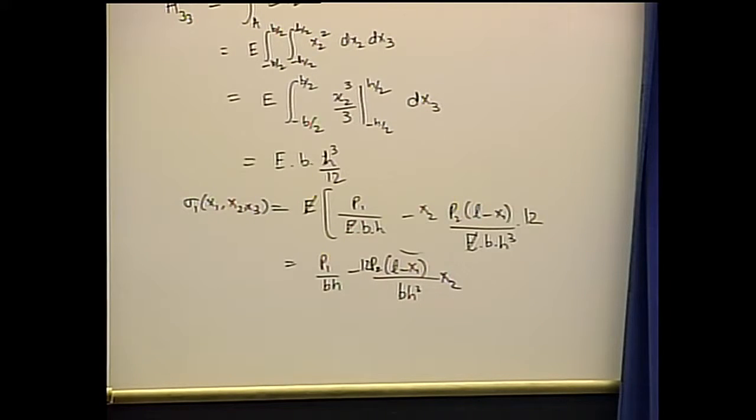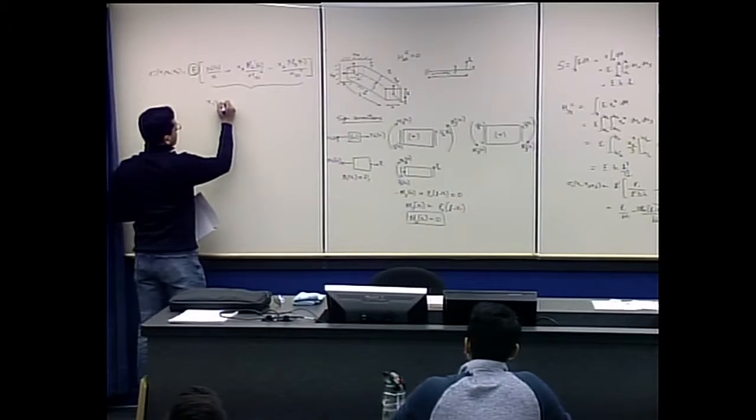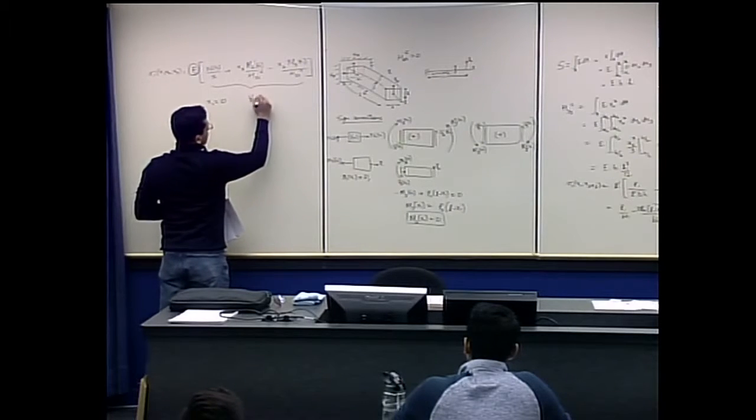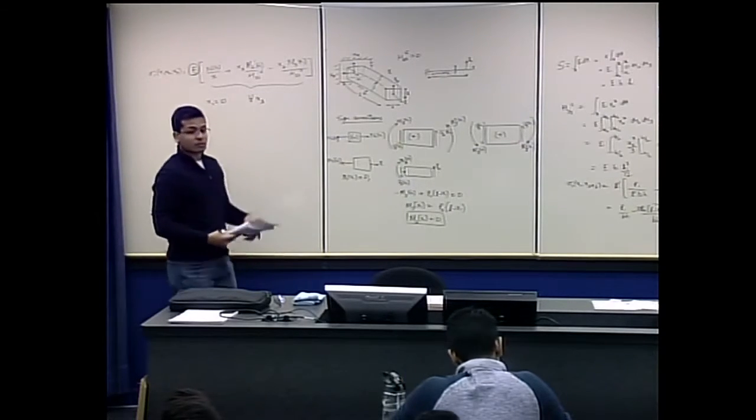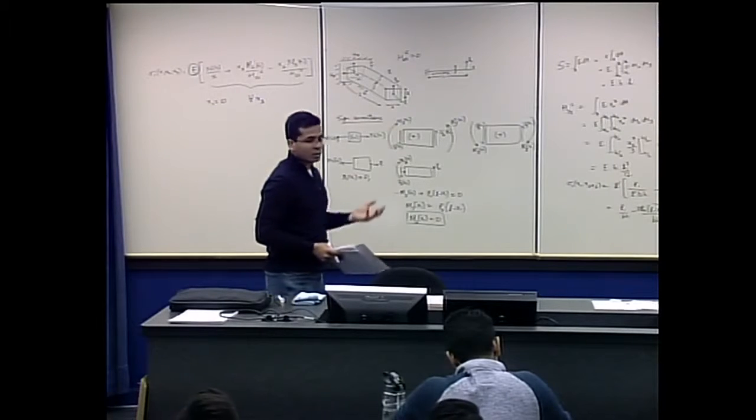It has to be 0, which was the answer given by her the first time. So x1 has to be 0 so that the stresses are maximum at the root, but we have not identified a location yet. We have identified that for all values of x3 and x1 equal to 0 stresses will be maximum, but we are missing information about x2.